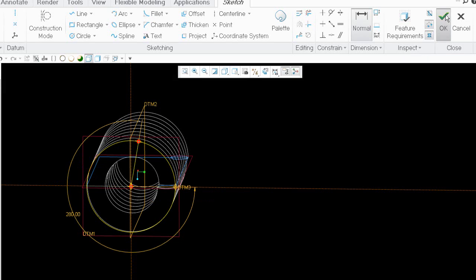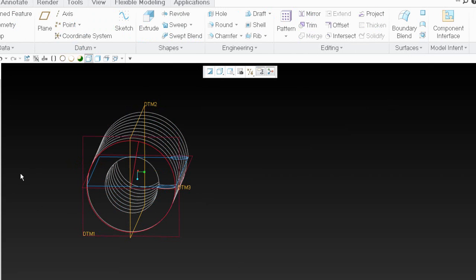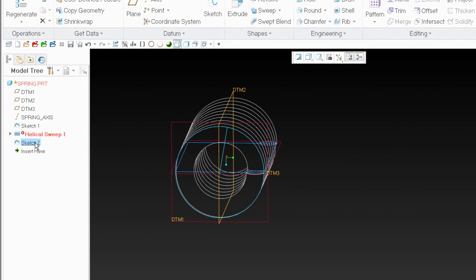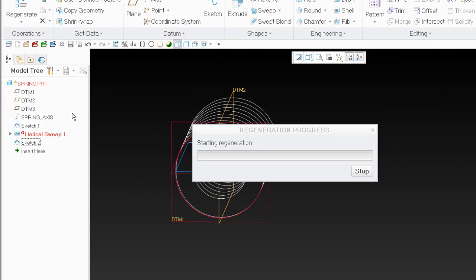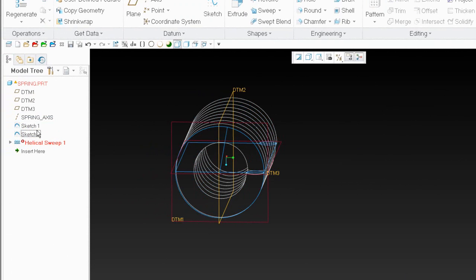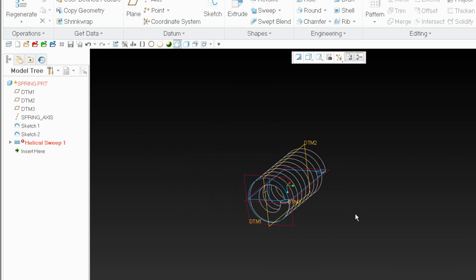And I'll show you, we're going to do that in a minute. We're going to go ahead and put that grind angle in. I'm going to need this to go before the helical sweep. Put this before it. Okay. So I got those two together. I'm going to make a group out of those later because these two sketches are actually going to have all my nominal dimensions in them, just these two sketches. I'm going to create another one later, but that's not for the nominals. These two dimensions are going to create all my nominals.